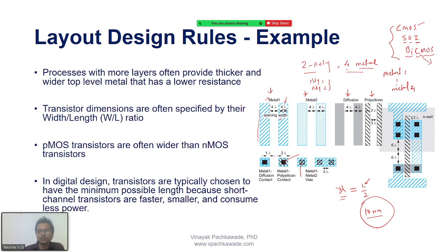If my circuit has two metal lines adjacent to each other, the minimum spacing between them has to be satisfied, which is again 4 lambda. Metal layer 1 is shown by these lines. I have used the same color but a different way of showing the metal 2 layer. The rules are the same here. What if I have more layers, like metal 1 to metal 4?